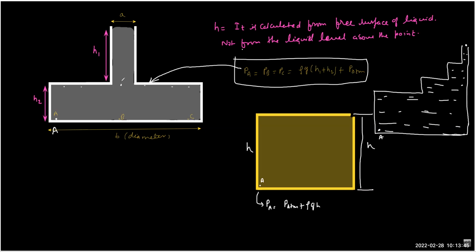So at this level, we can say pressure is how much? Rho g h1. Correct. So the wall at this level will exert extra pressure of rho g h1, and then the liquid column will add up to rho g h2, and the sum is rho g h1 plus rho g h2. So you can say that the mismatch is due to the wall. So we can in fact calculate what is the pressure exerted by the wall, and the answer is simple.